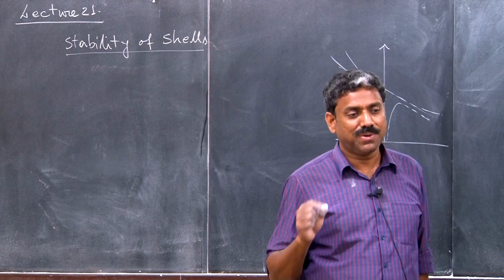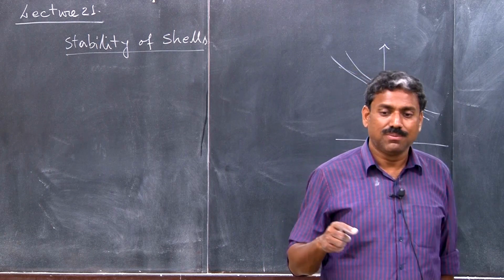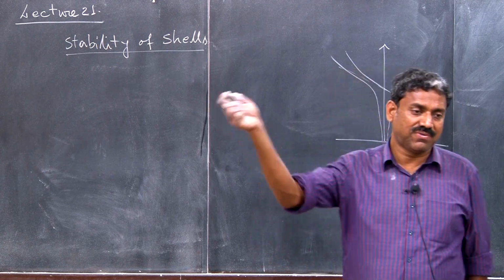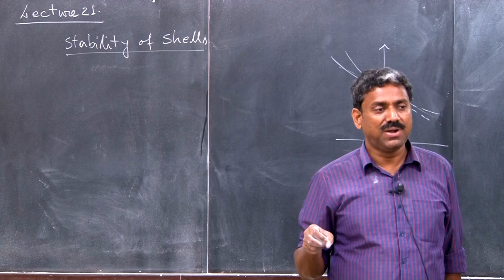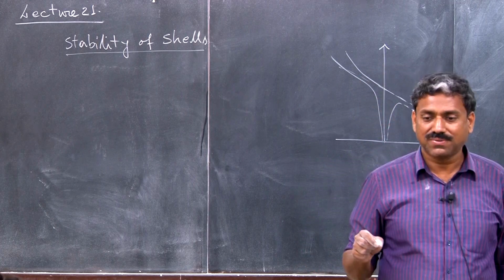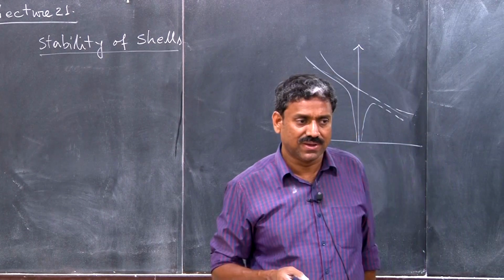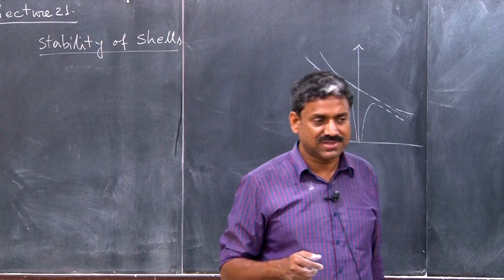Individual buckling modes are imperfection insensitive, following a 2/3 power law, and the critical load increases with imperfections. But as soon as they are coupled, because of modal interaction, they become imperfection sensitive. That means the critical load reduces with increasing imperfection.